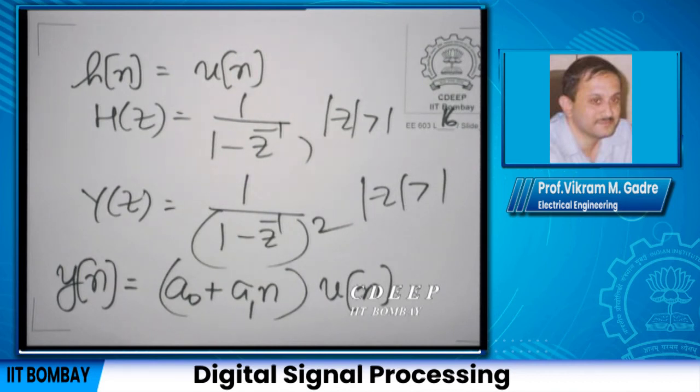Here is a system where the input of course has a pole co-located with the impulse response, it is the same place. If this were to be treated as an LSI system with this impulse response, that LSI system is unstable, because the impulse response is not absolutely summable. So, it is an unstable system.